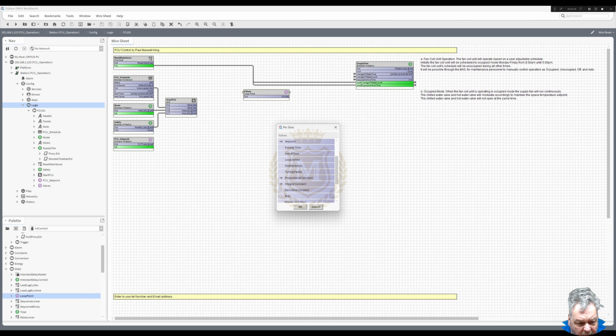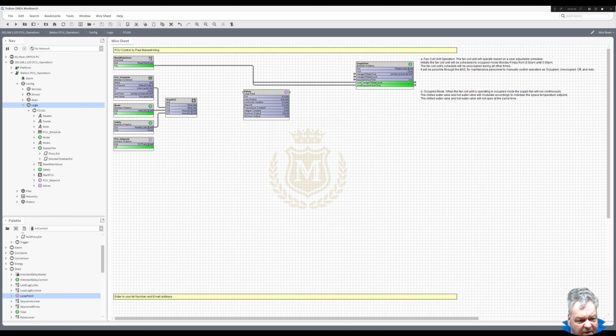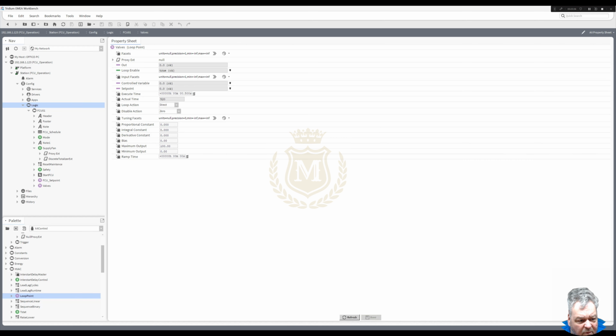We've put our prop and our int in there, and we'll do our minimum and maximum, not that we're going to be changing anything there, but you are going to see that I'm going to change that to -100. I normally use 2 for prop, I'm going to put something like 6 in there, and I normally use a 1 for integral, and I'm going to put something like a 3 in there. Save that.